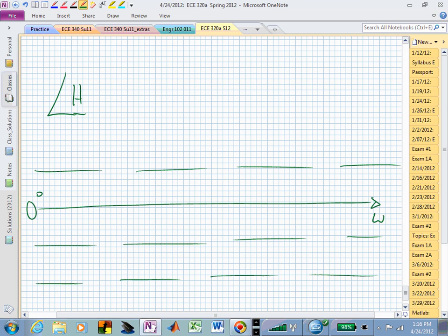If you now had to sketch -1 in the complex S-plane, you would say, oh, that's that point over here at -1. So that has a length of 1 and an angle of -180 degrees, and I'm going to be negative again, okay? So you'll just have to tolerate me for the rest of the semester on my negativity, but that's now -180. That's the constant piece. The constant piece is now here, and that's for all frequencies. I'm going to say this is -90 and this is +90.